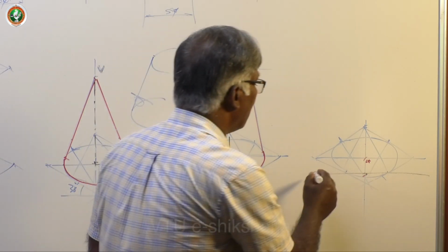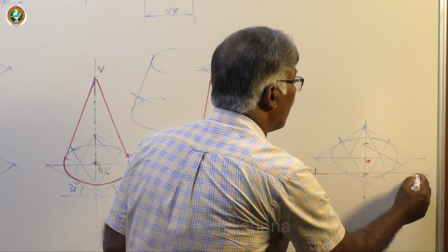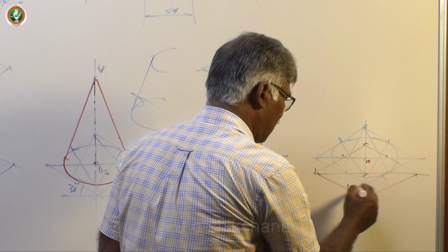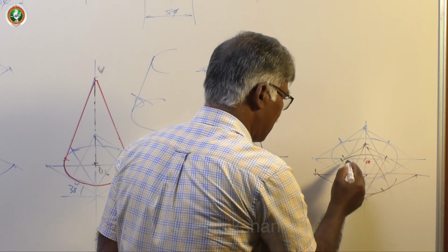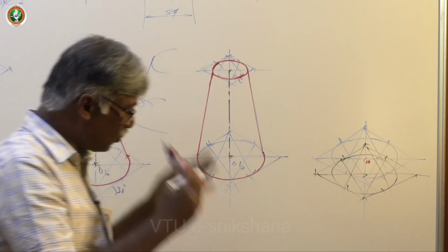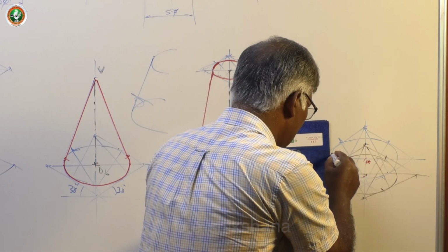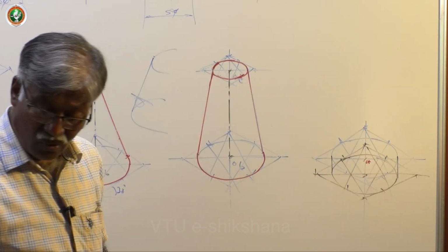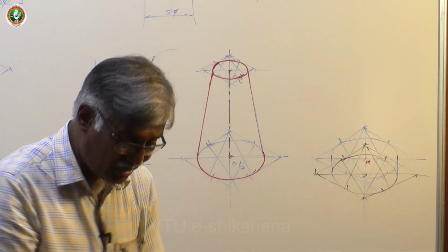Everything is same. Now draw this. You will get one more same figure. Mark, number of lines will be there. You must be very careful. Then draw ellipse. Yes. Now, how to complete? Draw 2 vertical tangents to these 2 ellipses. Okay. You must get vertical tangent only. Now, which one to keep dark? Out of the two, the top one you keep dark.